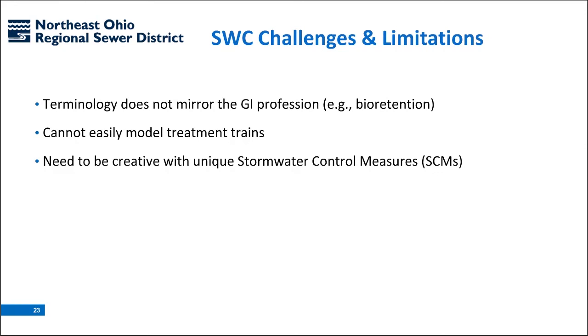So some of the challenges we have with using the calculator and some of its limitations need to be highlighted here. Again, terminology isn't consistent with what the GI industry uses, the best example being bioretention. So folks who use the calculator need to understand what the best fit LID control would be for their type of practice that they're proposing to use.